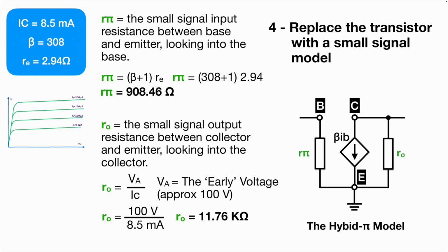So in order to make an ideal voltage source as ideal as possible, it needs to have as low an internal impedance as possible. And so an ideal one has zero, so it looks like a short circuit when you take the voltage away. But an ideal current source is the kind of opposite. If you want your circuit to have a fixed amount of current,